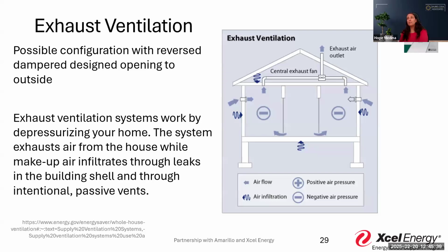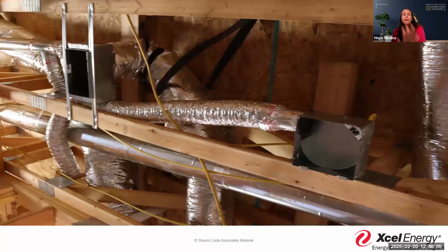And you have three strategies available. Most people, I will say, probably utilize the exhaust ventilation because you're already doing it. Although I'm seeing more and more people going with that balance, which would be an ERV and an HRV, because they look at it and it does so much more that it makes more sense to go that route. But if we have exhaust, we've got to think about how we are exhausting this out and what we are doing to ensure that we're not leaving a giant opening for air to move freely.